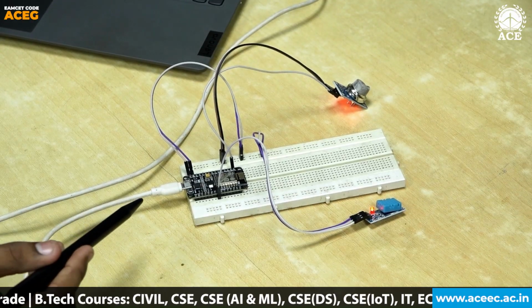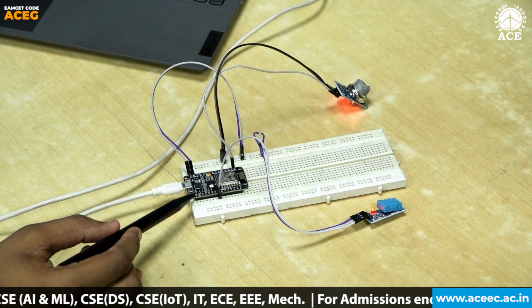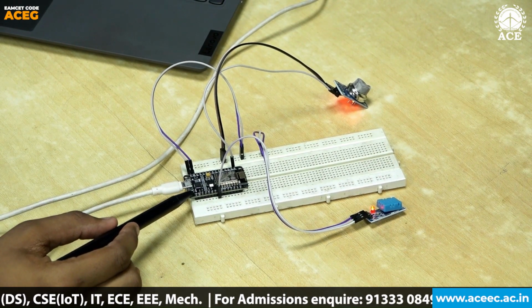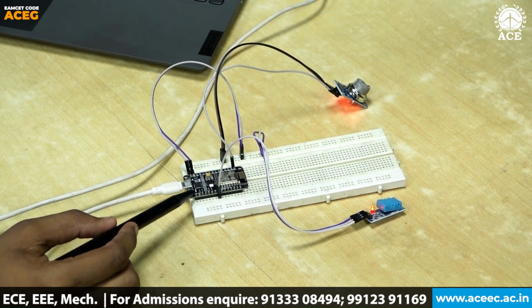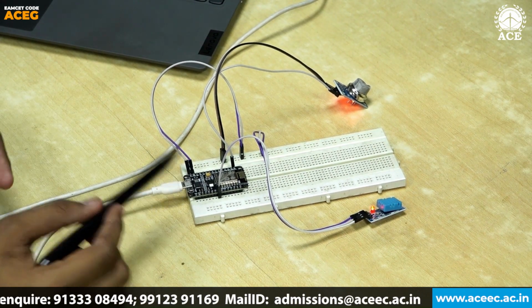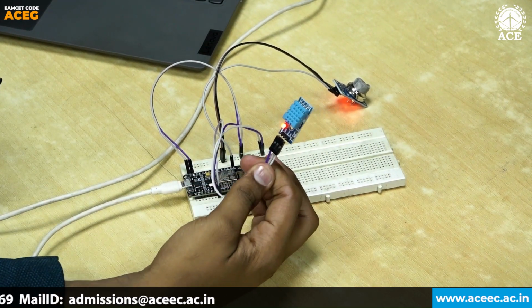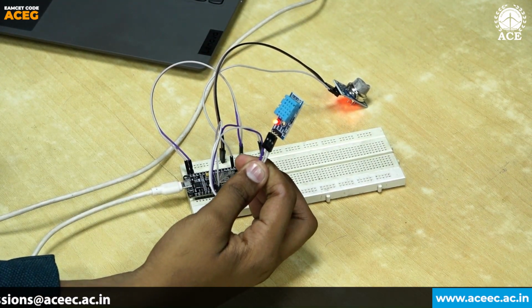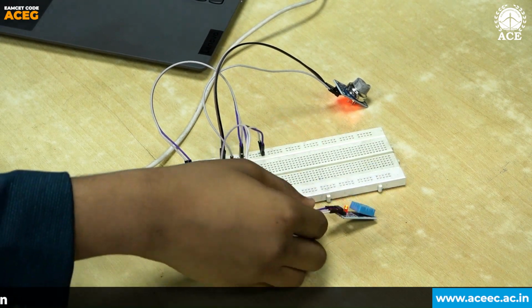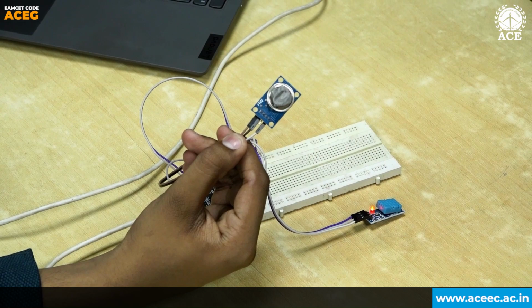This is the physical node we have discussed about earlier. Here, this is the brain of the node. This is the NodeMCU or ESP8266 board, which is Wi-Fi enabled, which enables us to get the real-time data from the sensors. Here, this is the DHT11 sensor, which is used to get temperature and humidity. And this is the MQ135 sensor, which is used to get the air quality index.